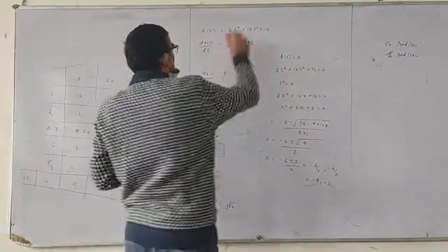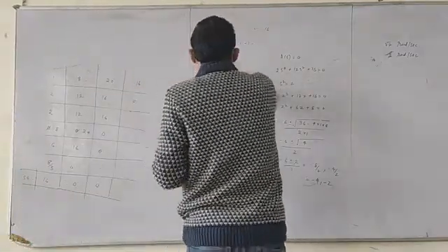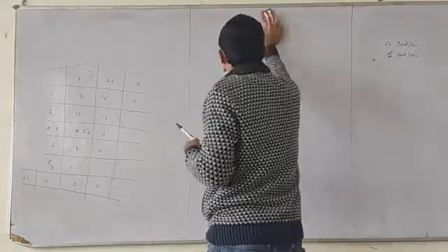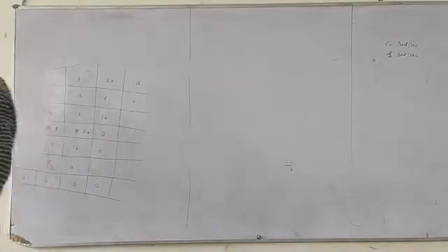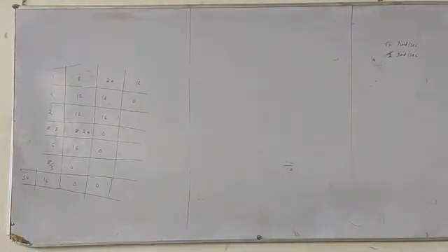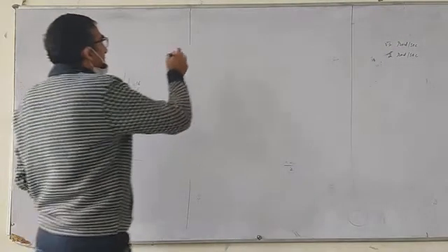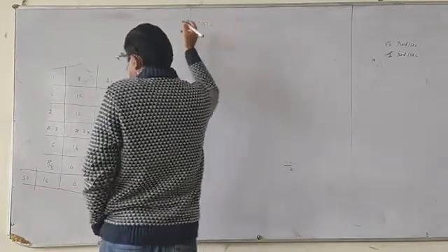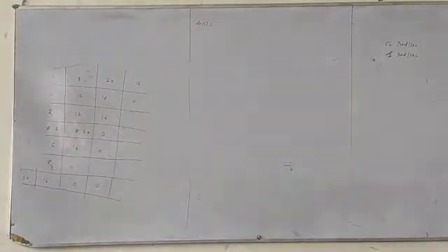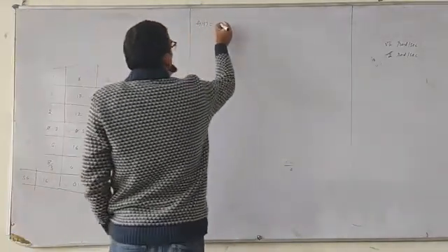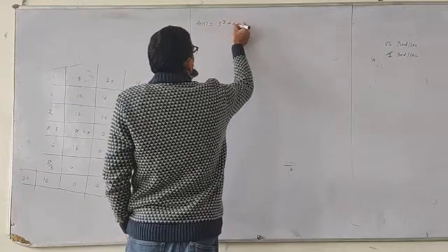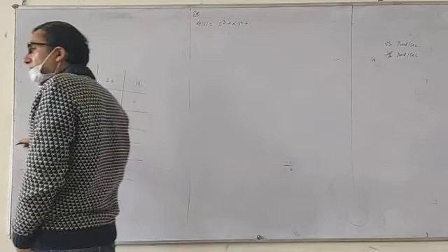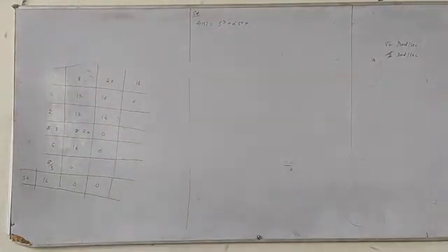Now this question was just to get you familiar with the row of zeros. He has given us a transfer function and we will write the characteristic equation. G(s)H(s) in this case will not be there. So this will be s cube plus alpha s square plus K s plus 3.